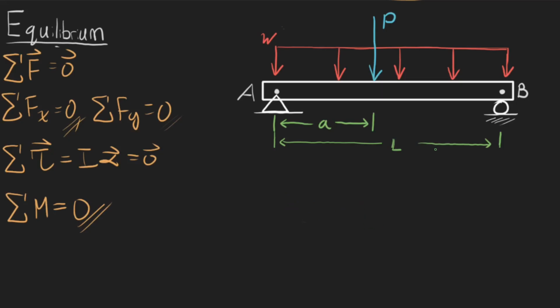And so this is one of the most common things you're going to see in statics: we've basically got a beam right here that has this applied load. I think it's called a distributed load. Basically the idea here is that there's a weight distributed across this entire beam, and we have w to describe it. So this will have units of force per unit length, something like newtons per meter. The idea is if I multiply by an amount of length, it'll tell me how much force is across that entire area. I have an applied load P here, that's just a force.